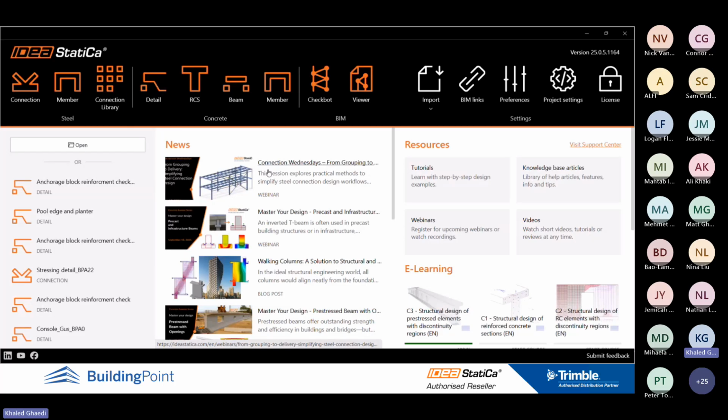The purpose of this demonstration is to let you know that you can bring the reinforcement from DXF as well. So I will go to the same DXF file, and then here I can just press Control and select all the reinforcement. Again, I put the reinforcement in this way just for demonstration purposes. And then accept. So right now I have it, and from here I can work with the reinforcement.